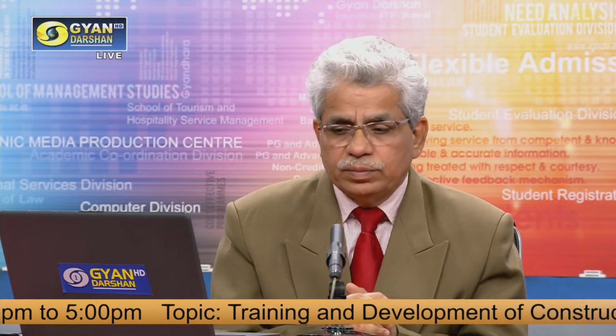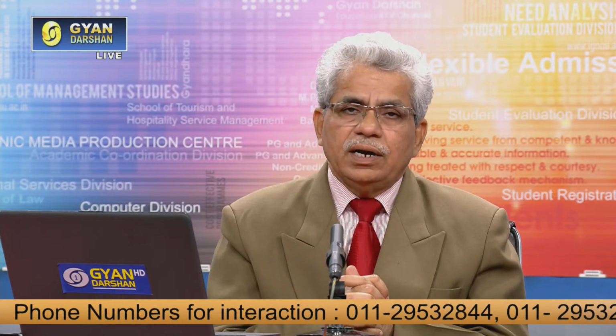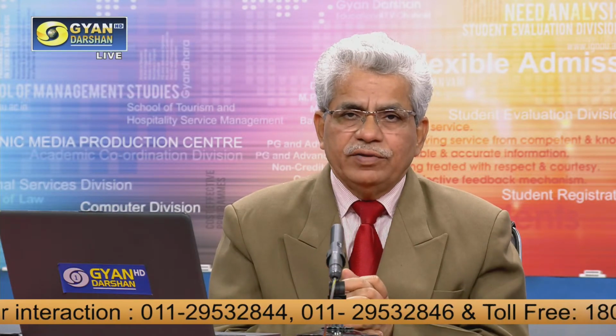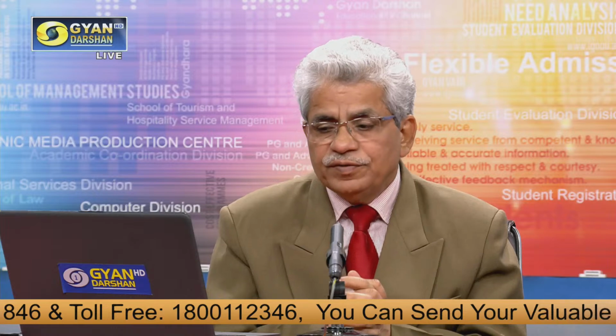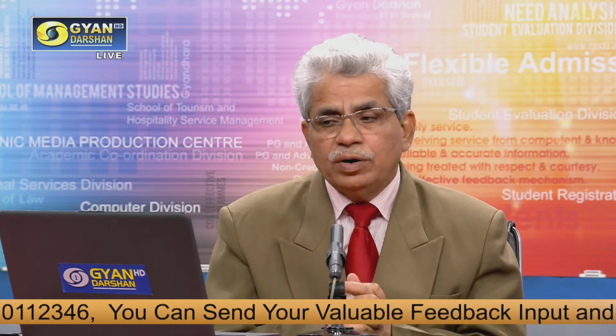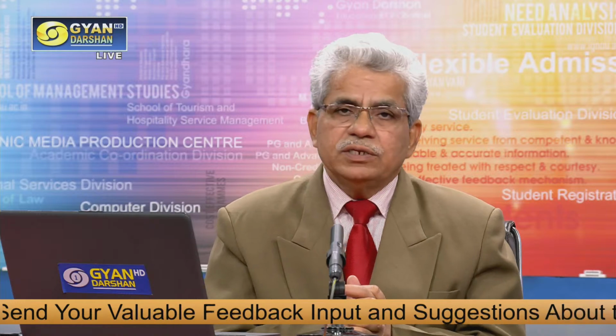So for that purpose, one should be very careful, and these workers should be told categorically what they should do to avoid any kickbacks or any electric shock. Then how to prevent these situations, they should be told. So what can be done? Wearing of protective equipment, proper gloves to avoid any electric shock, and proper gripping, having the proper position while using these equipment. Such things should be told to the workers. So that is the importance of training for power tools handling.